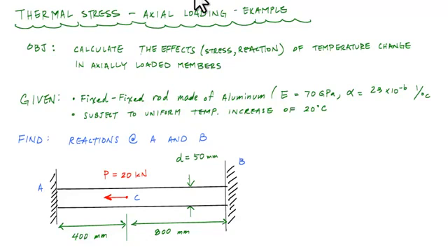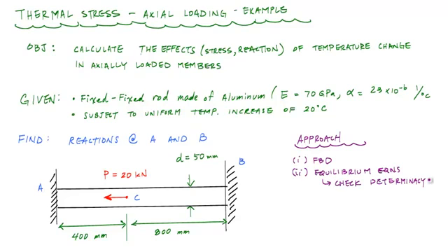And the way that we're going to do this is first to look at or draw a free body diagram and look at the equilibrium equations and find out that this thing is statically indeterminate. With a temperature change and a statically indeterminate component, we're going to experience thermal stresses.